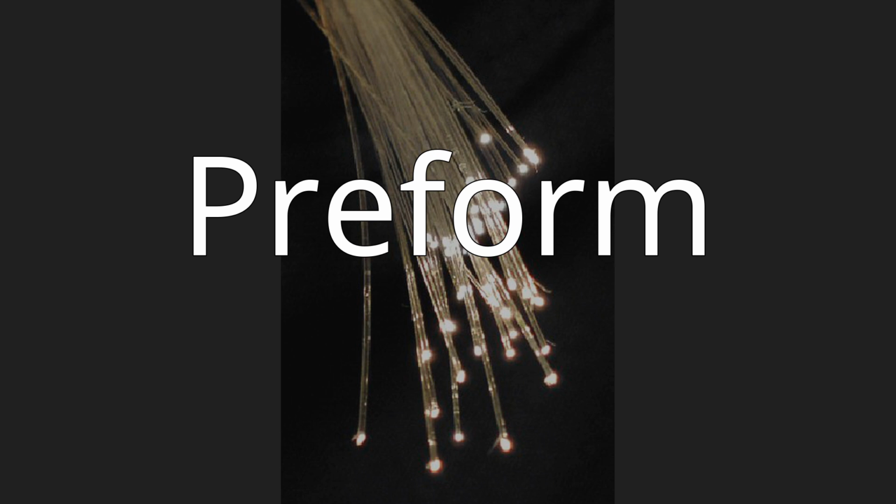deposition. With inside vapor deposition, the preform starts as a hollow glass tube approximately 40 centimeters, 16 in long, which is placed horizontally and rotated slowly on a lathe. Gases such as silicon tetrachloride SiCl4 or germanium tetrachloride GeCl4 are injected with oxygen in the end of the tube. The gases are then heated by means of an external hydrogen burner, bringing the temperature of the gas up to 1900 K, 1600 deg C, 3000 deg F, where the tetrachlorides react with oxygen to produce silica or germanium dioxide